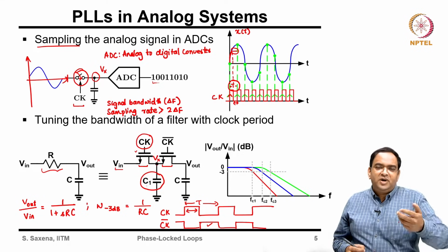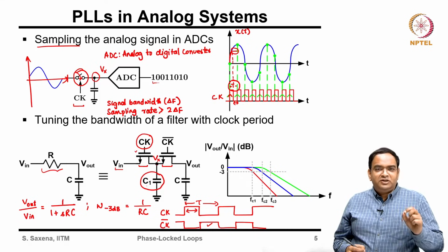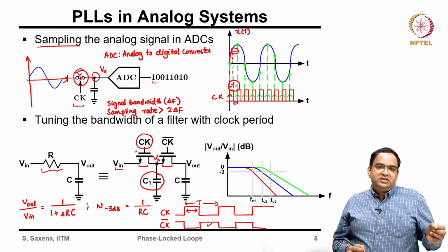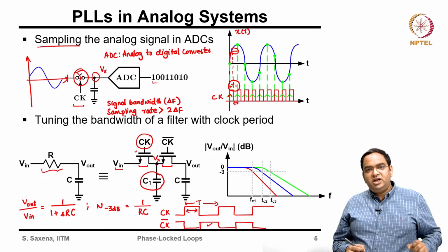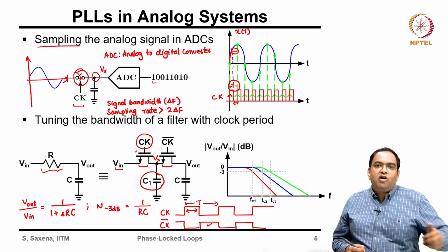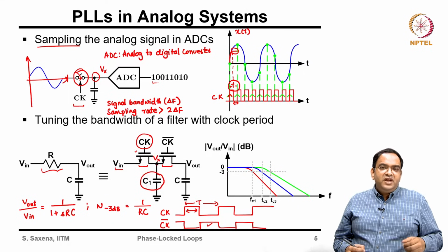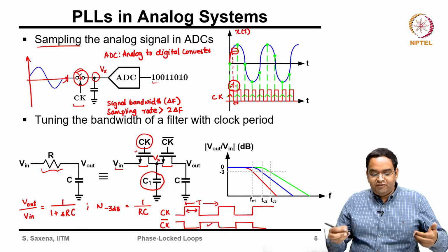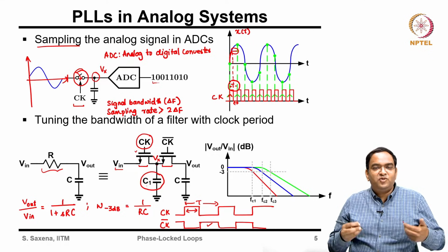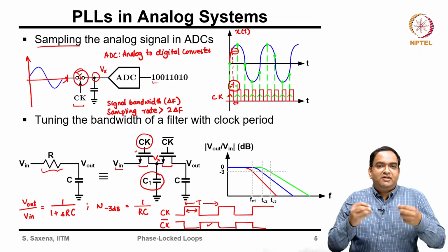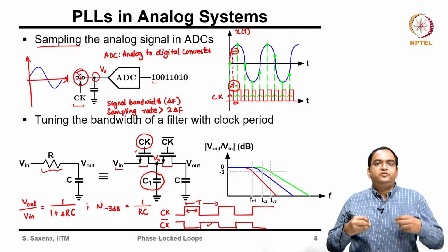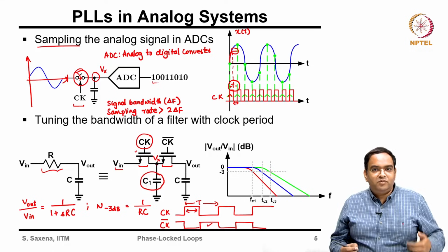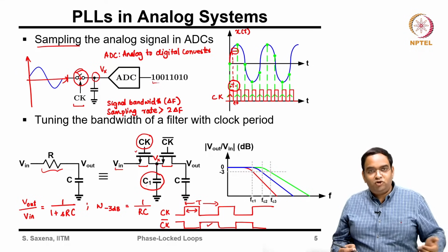Okay. So, just think about it, you have a capacitor, you are switching back and forth between two supplies, right. It is taking charge from Vin and transferring to Vout, and if it is doing it more often, that means it is taking charge from Vin more often, that is, the time period is less. Every clock cycle it does it. If it does it more often, that means within the same time it is doing it more number of times, that means the clock period is low.